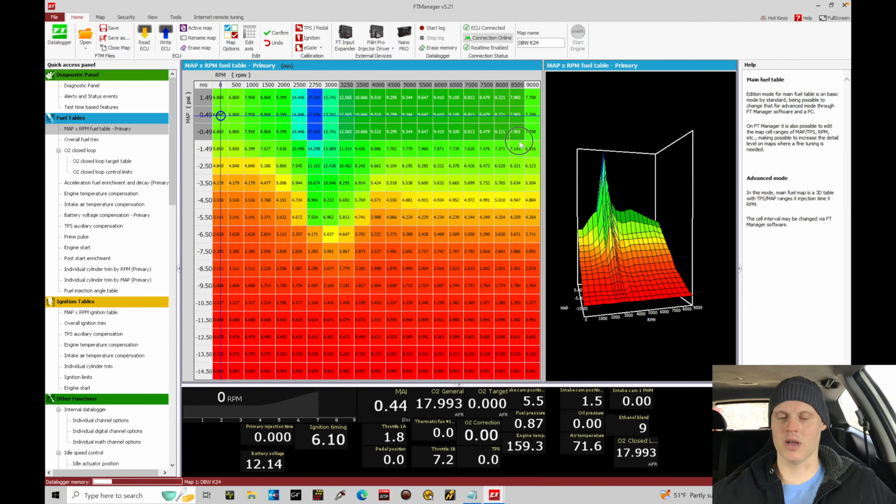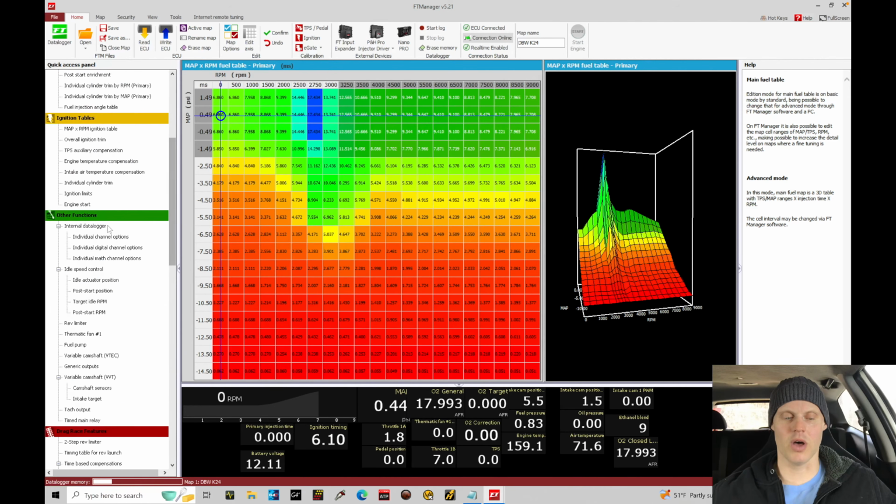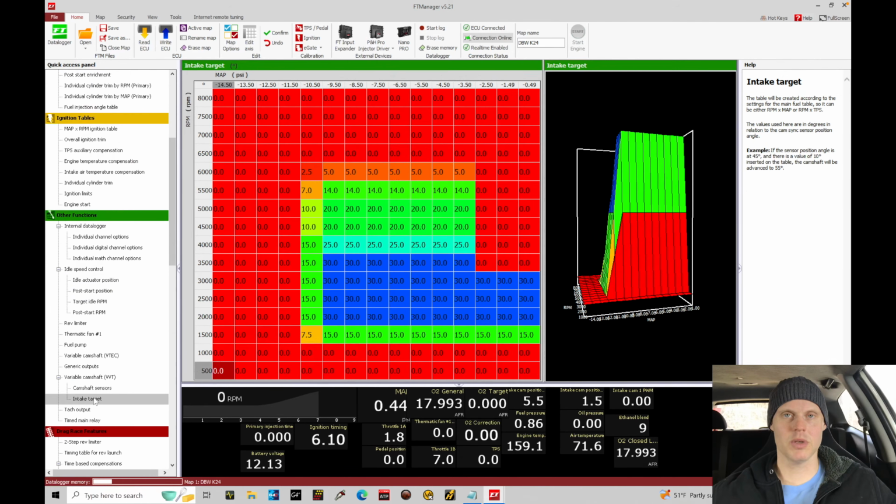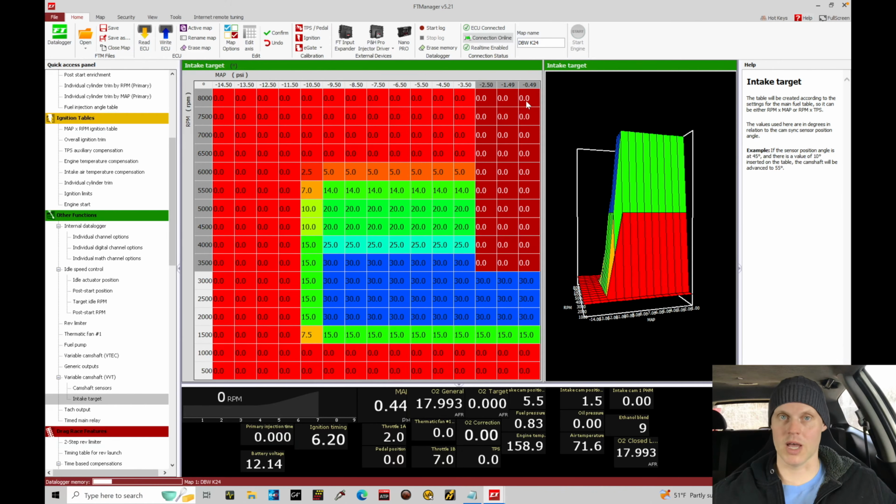We'll deal with everything above this point in the last few rows of the table to dial in our fuel table. So we want to baseline everything at 0 degrees, just as we did in the low cam tuning. Then we'll walk our cam timing up from 0, 10, 20, 30, maybe even 40, possibly 50. I have a 50 degree VTC gear installed on the cam, so I do have the ability to go up that high. We'll have to see how the engine responds.